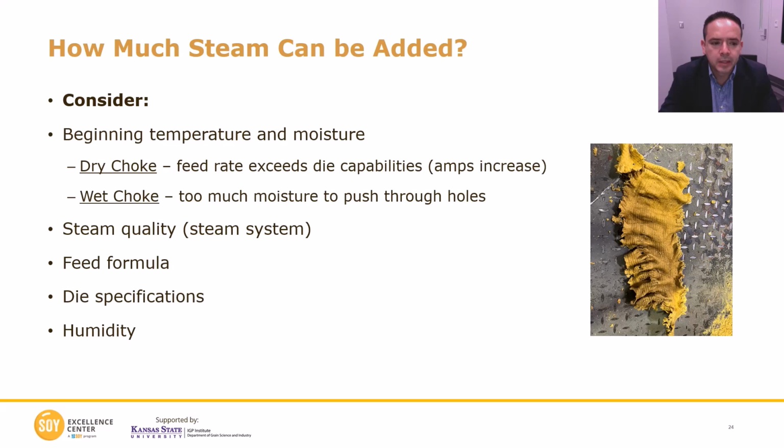If you have too much moisture, you are going to have a roll slip, what we call a roll slip. Don't forget that phrase. That happens when there is too much moisture in the mill. Also, you need to evaluate your steam quality. As I was telling you before, if you have poor quality steam, then you are not going to be able to add much of it before you plug the pellet mill.